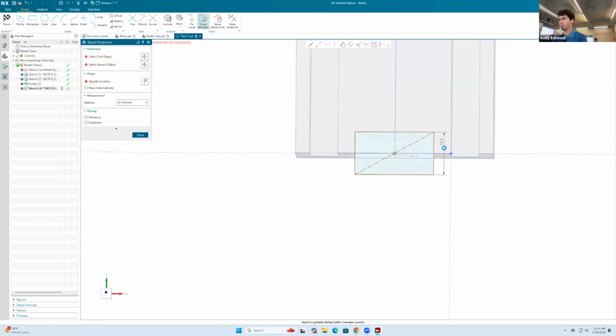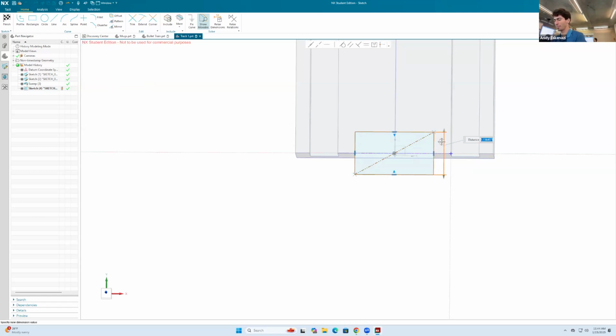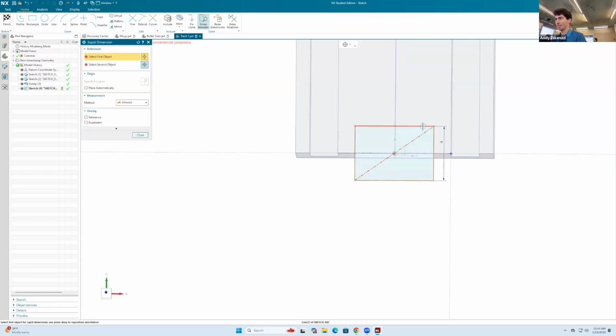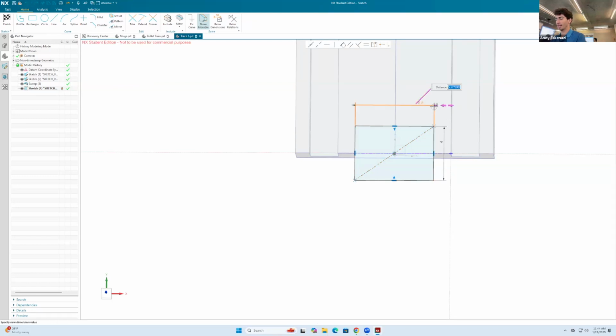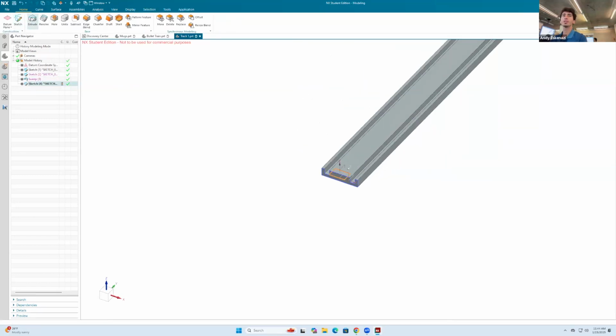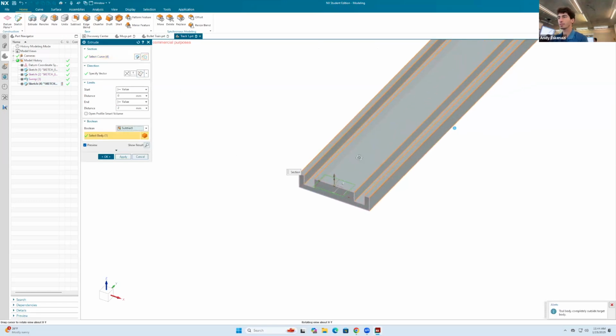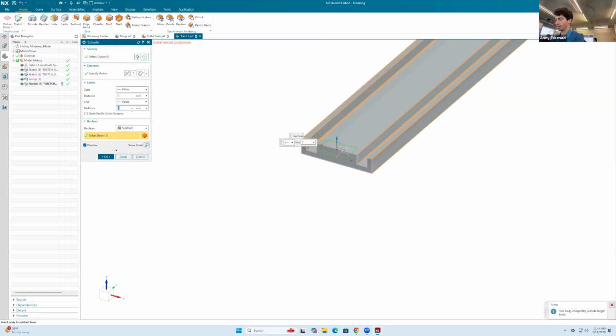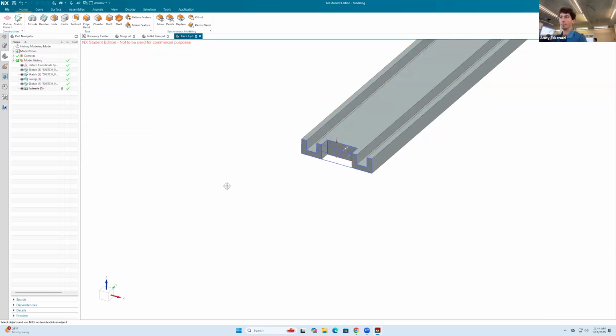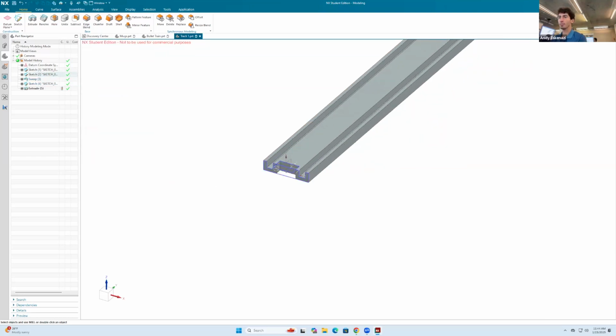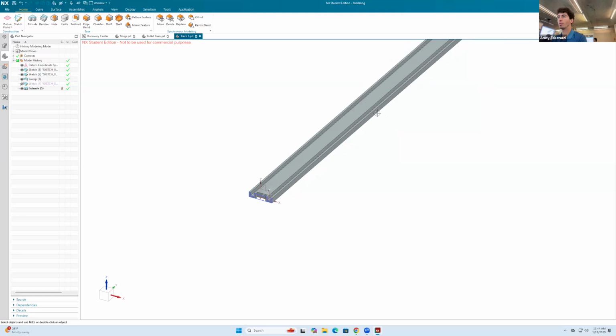Go 4. Then maybe we could say that is like 6. I go here to finish, and I'll extrude cut. I'll say subtract by -3. Okay. Let me just hide that for a moment.